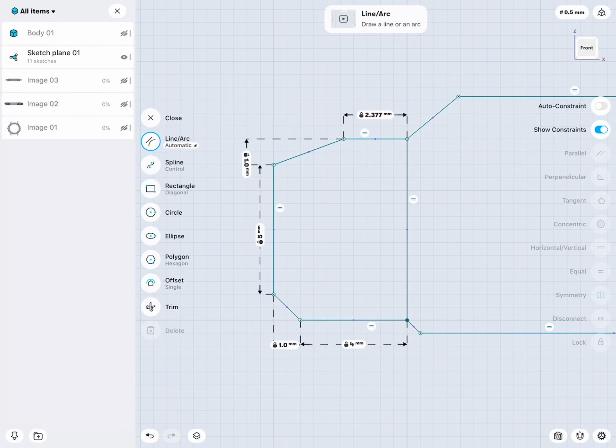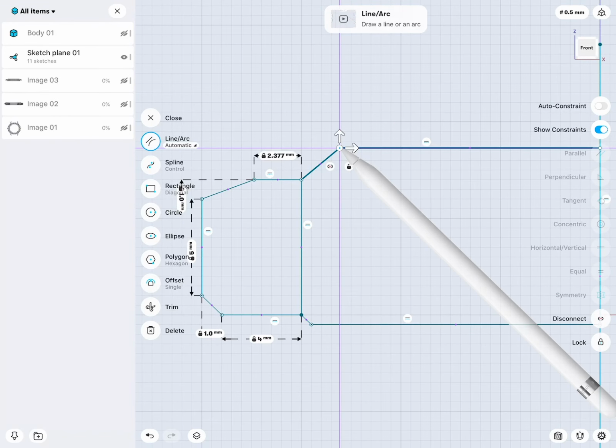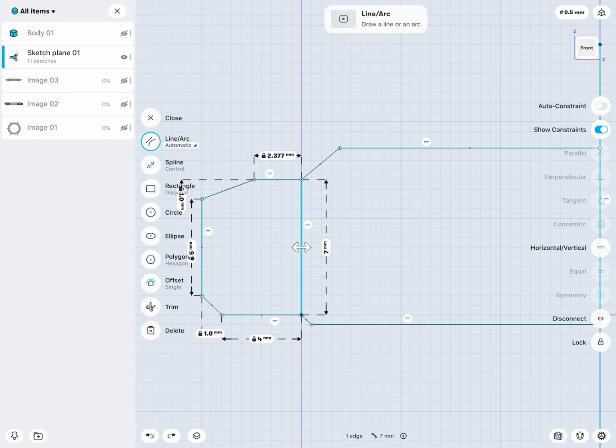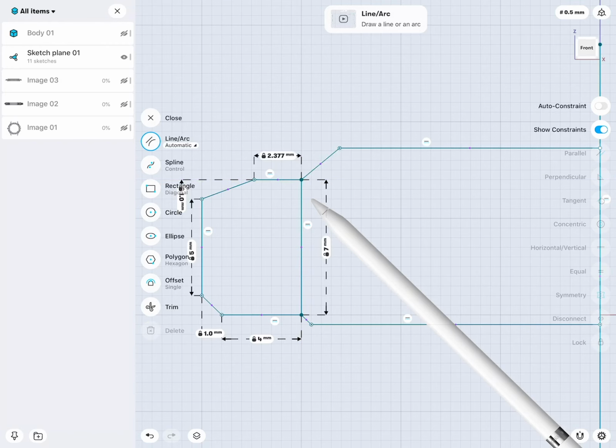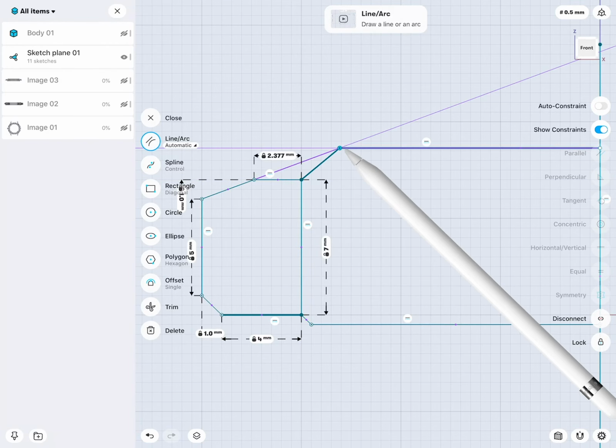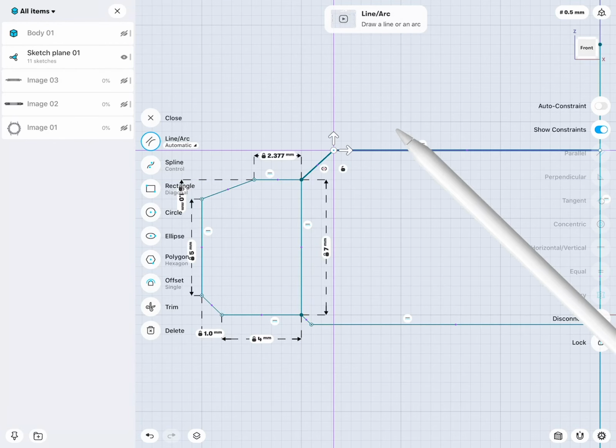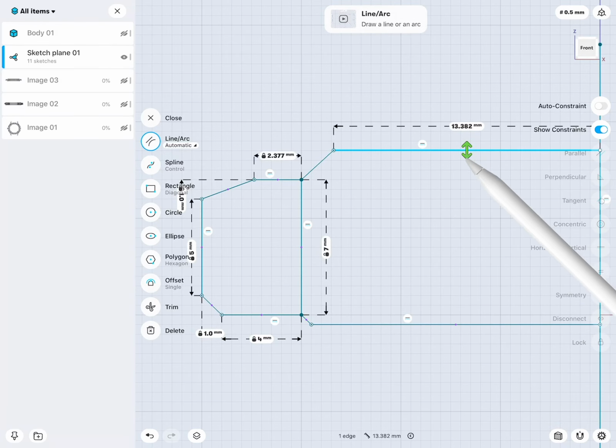Very good. So now when I move this, all this adjusts a little bit. It's also because here this does not have a dimension. So I can actually lock the movement by adding dimensions, or I can also lock by selecting a point and locking it. And now you see that doesn't do anything anymore. Okay.